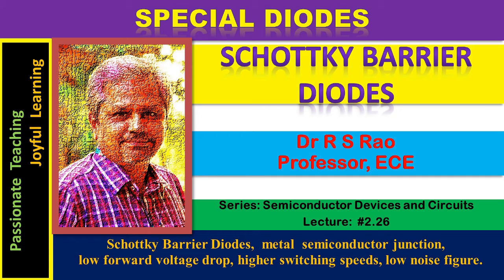Special diodes, Schottky Barrier Diodes, series on semiconductor devices and circuits, lecture number 2.26. Schottky Barrier Diodes belong to the category of special diodes. They are made out of a piece of metal and a piece of semiconductor. In that way, they are different from ordinary PN junction diodes, which are made with two pieces of semiconductor.